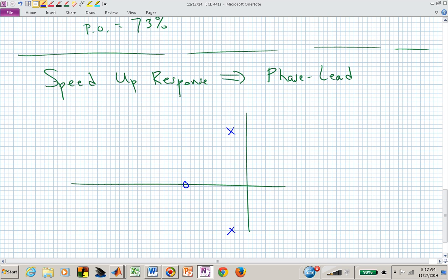But now do you see what the root locus would be for this configuration of poles and zeros? What would the root locus look like? Do I have any real line segment that belongs to the root locus for this particular pattern? And this pattern is not final, but just to get a feel for it, can I pull the branches of the root locus over to the left further than -2?